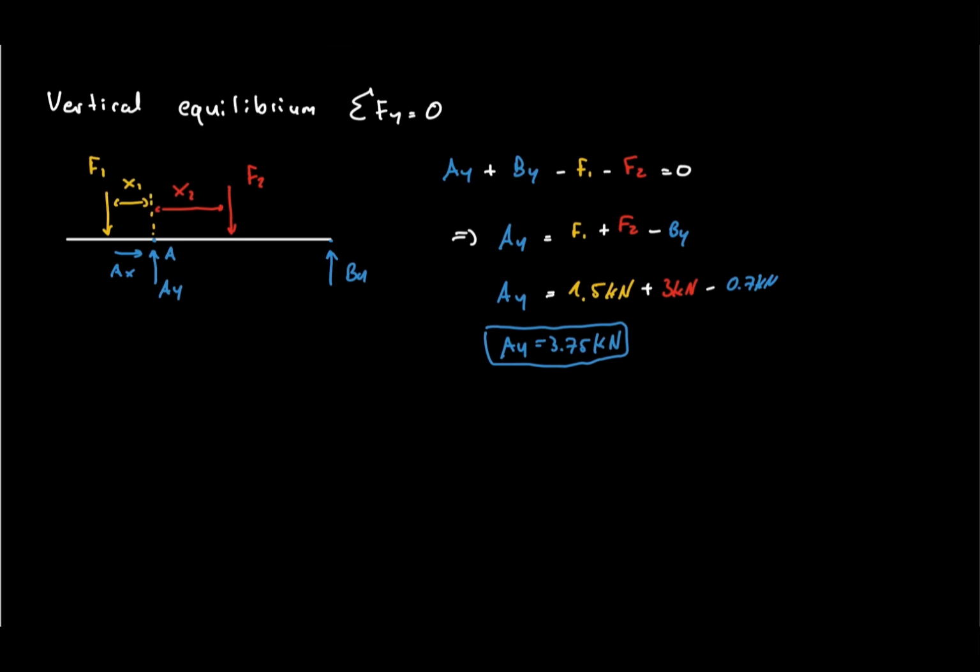The most important lesson is not the numbers. The important lesson is the strategy. Whenever you see a complicated distributed load, ask yourself whether it can be divided into simple shapes. Once you replace each shape by its equivalent force, the rest of the problem becomes a standard statics exercise.